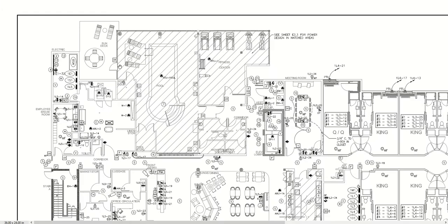And then another rule of thumb is in sizing these. For general electrical rooms, I usually try to ask for a minimum of 6 foot by 9 foot, which usually gives me plenty of room for whatever panels I need to put in there, maybe even a transformer. For the main electrical room, I usually ask for 12 by 10. I don't always get these requests, but when we're doing space planning, that's what I usually initially ask for, and I usually work around that.